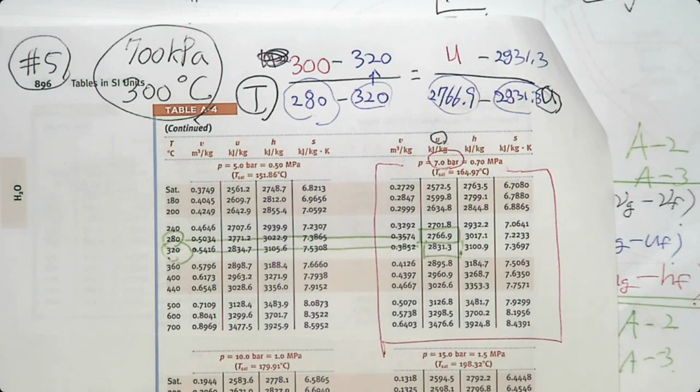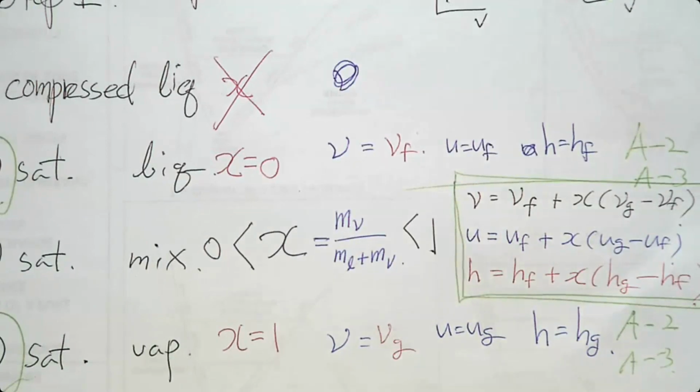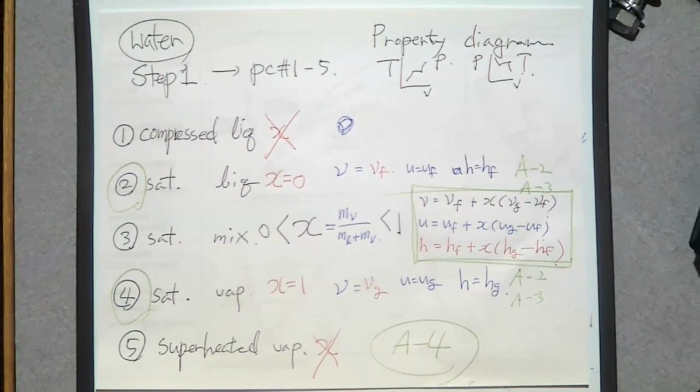Okay? Any question about linear interpolation? In your homework assignment, you may see some linear interpolation, so you can practice, right? But in your exam, I will do my best to minimize the number of linear interpolations because you're working in limited time, okay? So that's how you determine a property of saturated and superheated vapor, table A4.